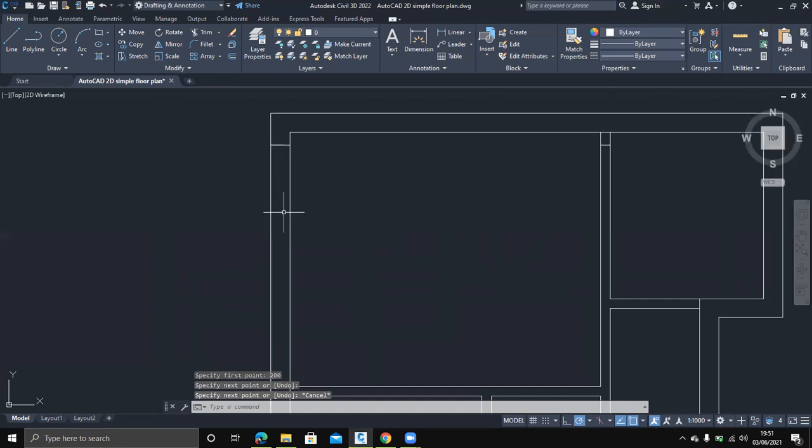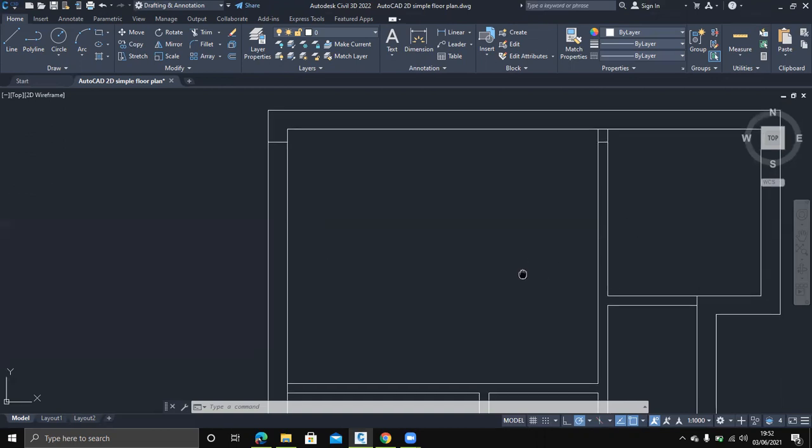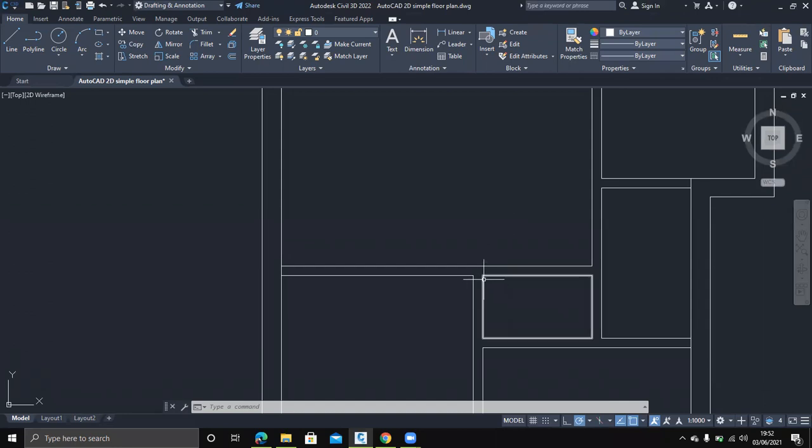So I will not draw the other side of the door, the trim that should be on this side, because I believe we can work faster when we do an offset, because all doors are actually 900 units. So if I use an offset command, I'll be able to offset these other lines that should be somewhere here faster without having to draw each and every one of them for each and every door. So let me just do it so that you guys can understand what I'm saying. There's another door right here, an extension of 50 units. I will draw it right there.